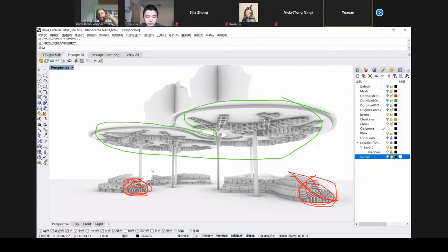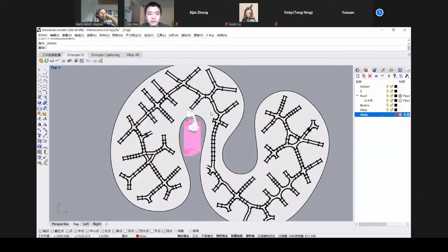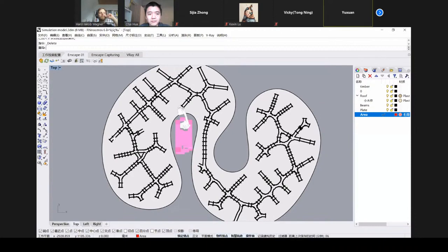Actually, I'm quite concerned about the fabrication process. Not just the construction. You first post it on the floor, and then fabricate on top and flip it. Yes, I want to place the whole roof on the ground and then place all the beams on the top of the roof, but it's actually the bottom of this roof. And when hung up, it will be flipped around and arranged.